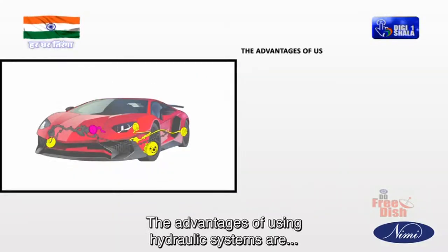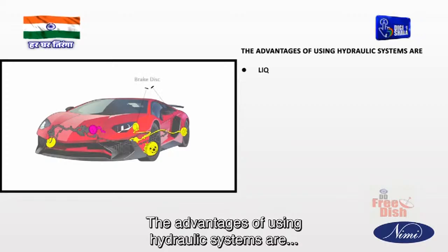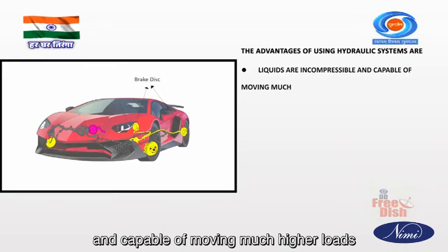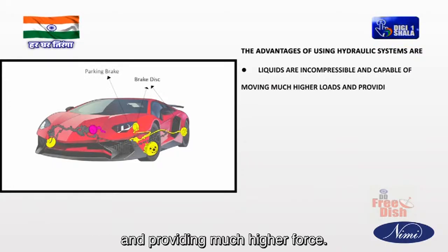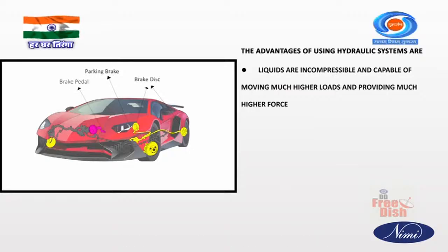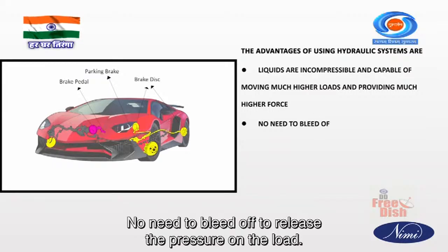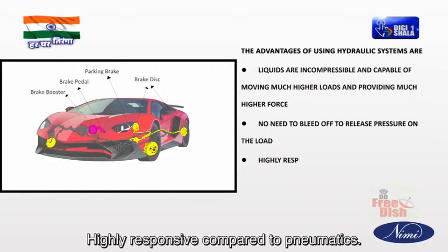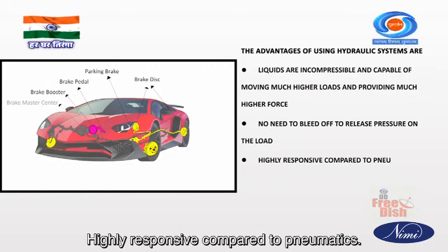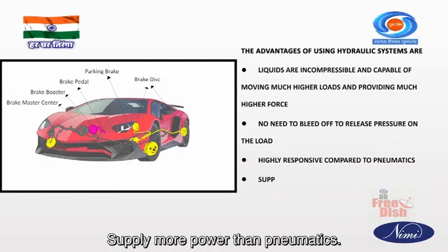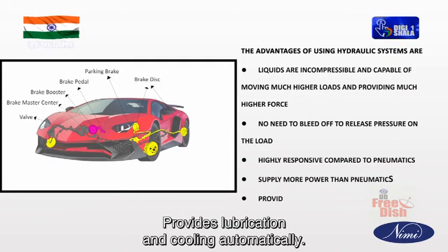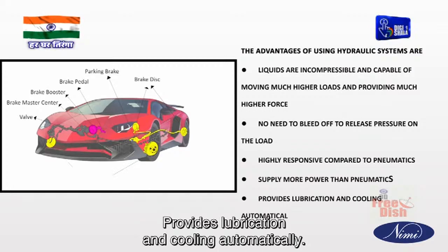The advantages of using hydraulic systems are: liquids are incompressible and capable of moving much higher loads and providing much higher force. No need to bleed off to release pressure on the load. Highly responsive compared to pneumatics, supply more power than pneumatics. Provides lubrication and cooling automatically.